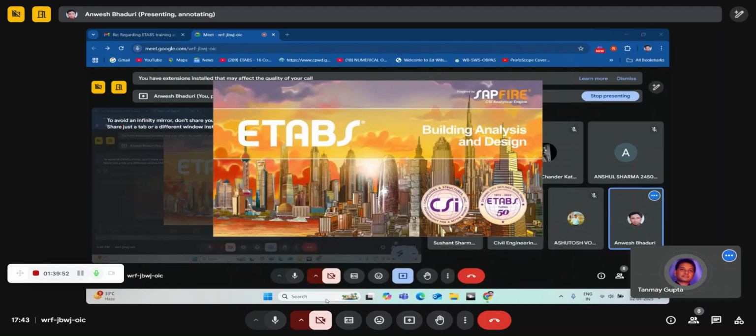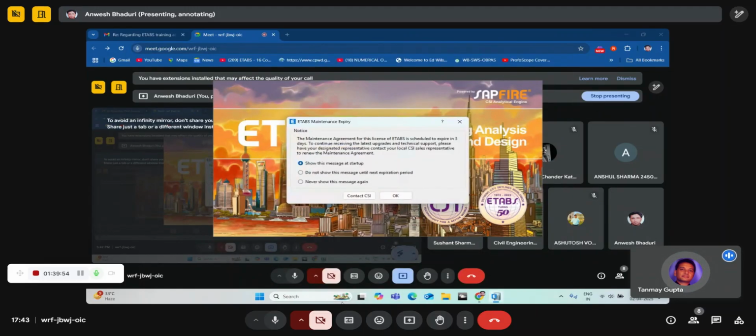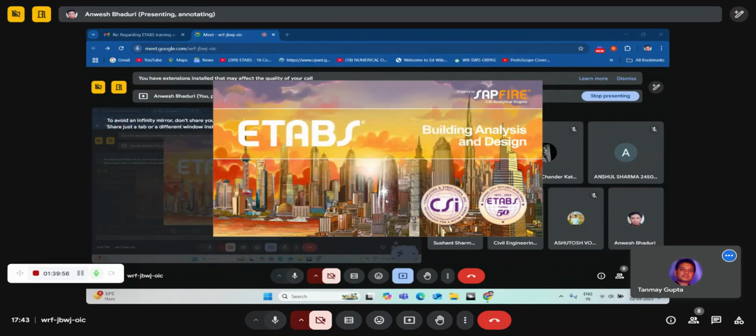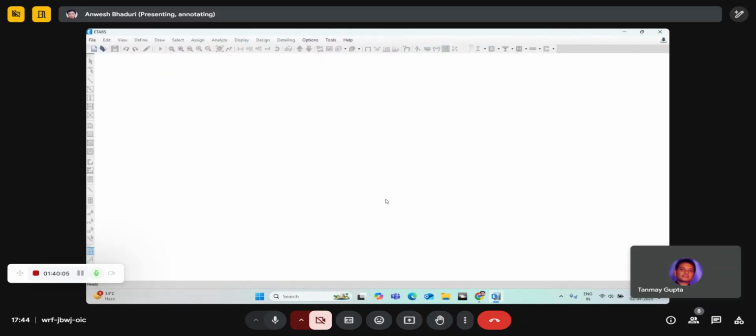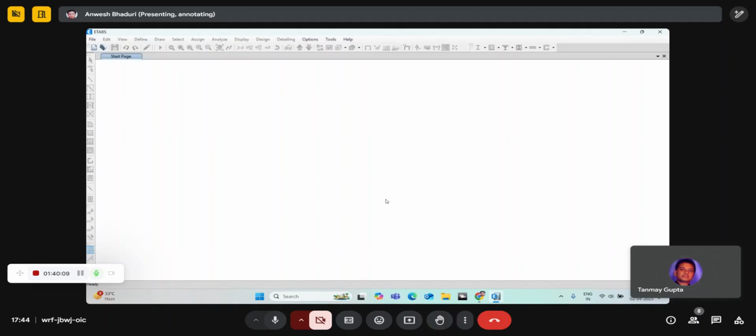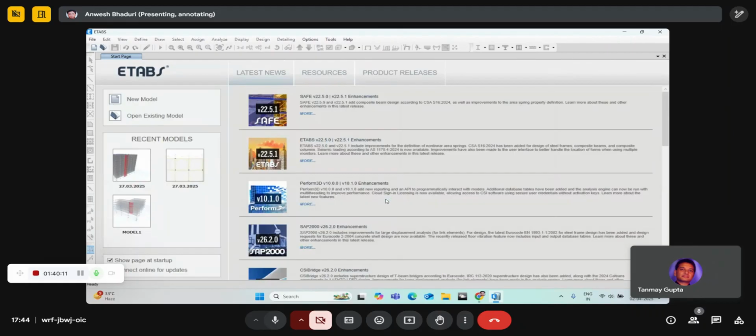After this, do we need to make a combination for this also, like TH plus CX? If you carry out linear time history analysis, it doesn't make much sense because accelerations are anyway in different directions. In that case you don't have to have those combinations that we had already defined. But if you're having a time history function defined, it's always better to go for nonlinear analysis.